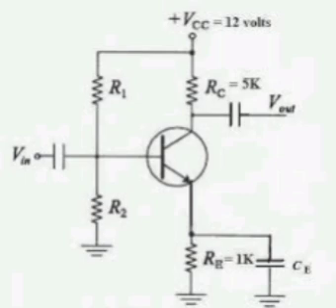Apply KCL at V2. I2 equal to (V2 minus 2V1 minus V1) whole by 1 plus V2 by 2. I2 equal to minus 3V1 plus 3 by 2 V2. Y parameters equations: I1 equal to Y11 V1 plus Y12 V2. I2 equal to Y21 V1 plus Y22 V2. Comparing equations 1 and 2 and 4, then you will get the Y parameters.